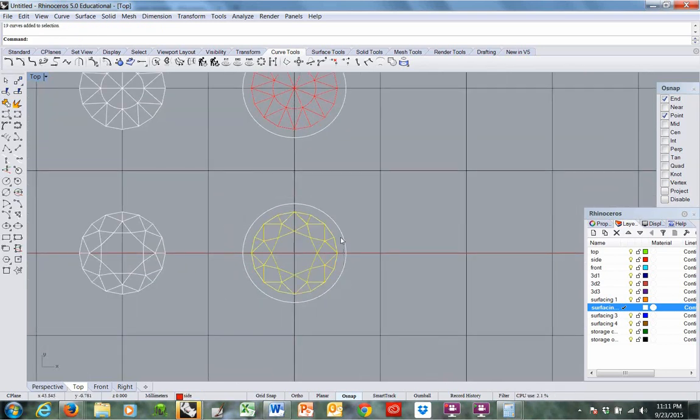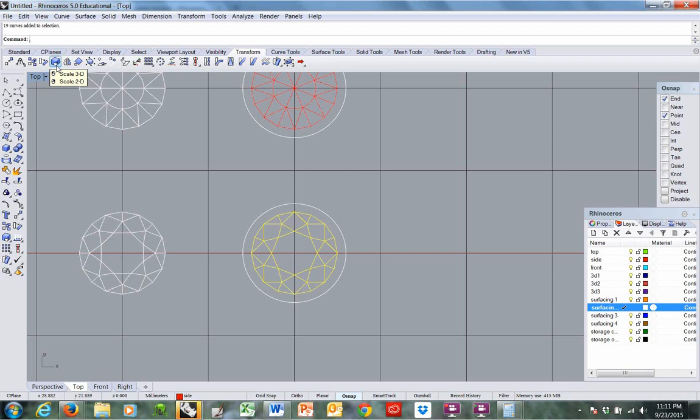I'm going to grab this drawing. We're going to use a scale command that we have yet to use, non-uniform scale. If you click the pop-out button on scale, pick the second to the last, non-uniform. This allows you to scale an object in each of the three different axes independently. So you need an origin point, like with every scale command. I'll use grid snap. I don't want to change the dimension in this direction. Okay? I want it to stay at 10 millimeters.